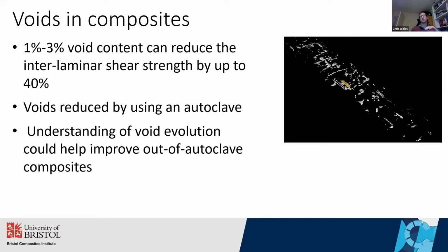While composites are typically strong in plane, where you've got the fiber direction, they're weaker out of plane, where you're relying more on the matrix strength. A 1 to 3% increase in the void content in your matrix resin area can greatly reduce the interlaminar shear stress, and this in turn lowers your overall mechanical properties by about 20%. To get around this, you'd have to increase the amount of composites you use in your structure, which increases the cost and particularly weight, which we're interested in for aerospace.